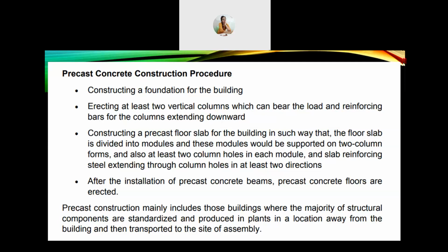And the last one, after installation of precast concrete beams, precast concrete floors are erected. So, precast construction mainly includes those buildings where the majority of structural components are standardized and produced in plants in a location away from the building and then transported to the site of assembly.